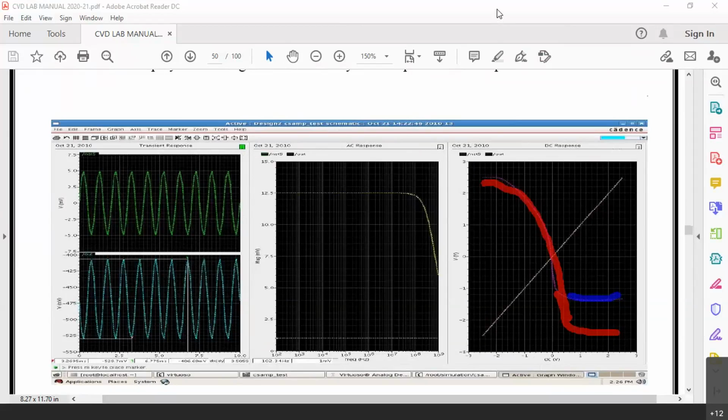For inverter, PMOS is connected to ground. Yeah, that is fine. But in the case of this amplifier, it is connected to minus 2.5, no? It has to go till minus 2.5, right? Because this is also an inverting amplifier only. Basically, inverter is also an amplifier. Only thing is, we use inverter in two states. Otherwise, to the same inverter, if you give a small sine wave at the gate, that is also going to amplify to some extent. Ultimately, amplification is nothing but switching only, right? Switching between lowest state to the highest state. That's all.